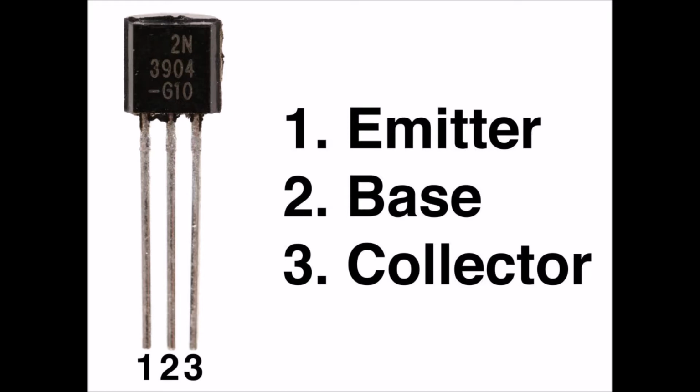Page 381 at the top. When the input signal to a transistor amplifier exceeds a certain critical maximum, we get a condition called overdrive. An overdriven transistor operates in or near saturation during part of the input signal cycle. Overdrive reduces the overall circuit efficiency, causes excessive collector current to flow, and can overheat the base collector junction. Sometimes overdrive can physically destroy a transistor.